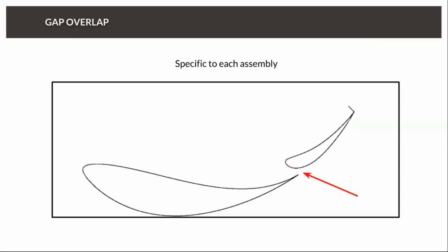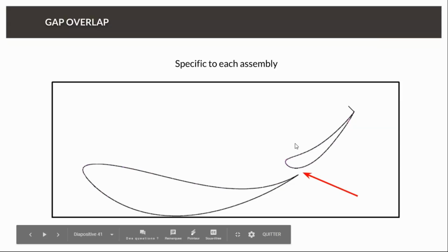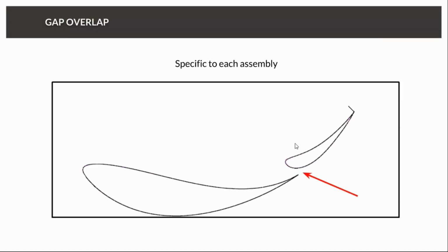And the same philosophy can be extended, and you can start to increase the curvature by rotating the flap more, curving the main plane more. There again, there will be a limit of separation, and then you can put a third element if the rules allow it, or a fourth element. And there have been times in F1 in the early 90s when we had up to 12 profiles on the rear wing end plates, because it was authorized to have that many, and we could create downforce by this multi-element assembly.